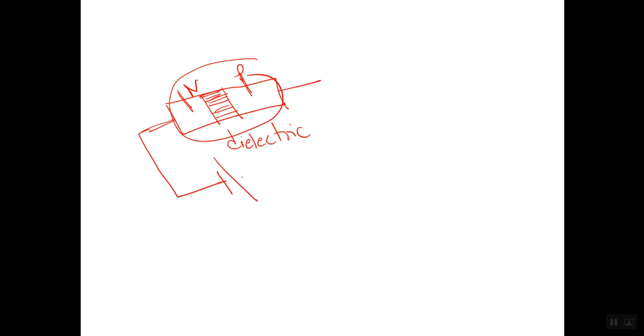It was connected like this in forward bias condition, P, and this was positive. So it was forward bias. In that condition, we learned that this depletion layer was very thin. It means the distance between these two plates N and P is small. Just think that this is a capacitor now, because it is behaving as a capacitor also at higher frequencies. So when the distance between these plates is less, as you know in forward bias the distance was very less, it offers more capacitance.